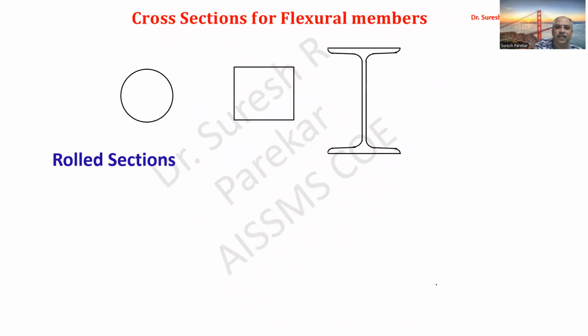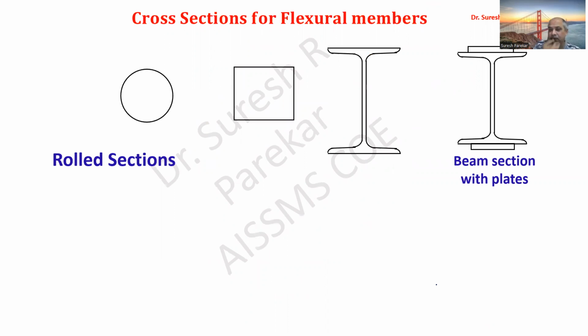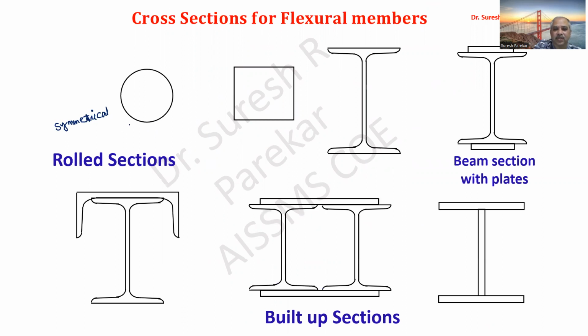So cross sections, if you see, we are generally not using angle sections. In flexural members, we are going to prefer symmetrical sections. Symmetrical sections we are going to consider in flexural members. And then we have built up sections. This built up section we are going to prefer as a flexural member for gantry girder, and we will see why we prefer this in gantry girder itself. But we require Zp top more, and therefore we go with this.